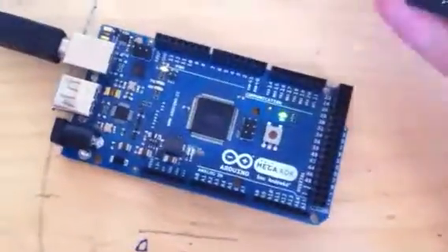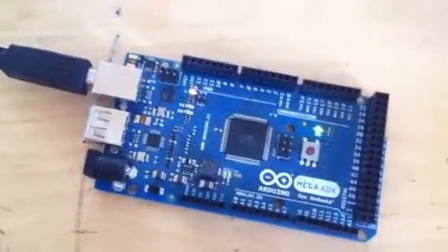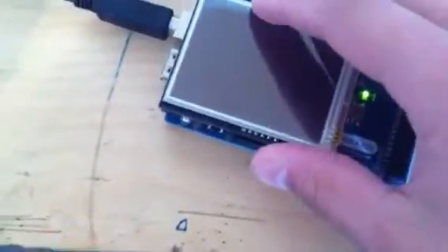So what I've got here is an Arduino Mega and the touch shield slide, and they've both got this same little Atmel 2560 chip on them. So this actually acts as a graphics processor and receives instructions and does a little bit of processing, basically just to get the images on the screen and whether or not certain values equal certain values. And this unit here, the Mega, will take all the various parameters from the car, like temperatures and whatnot, process them and then send them to the screen. So if we plug the screen in, at the moment I've just been working on the GUI, but I'll show you what I've got going here.